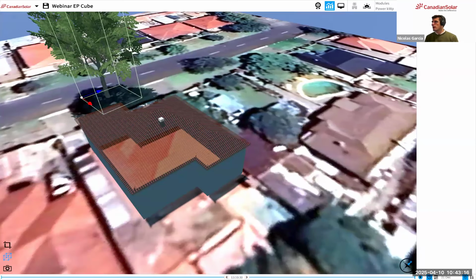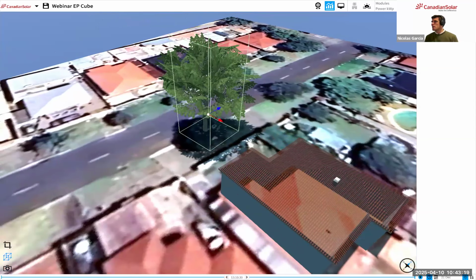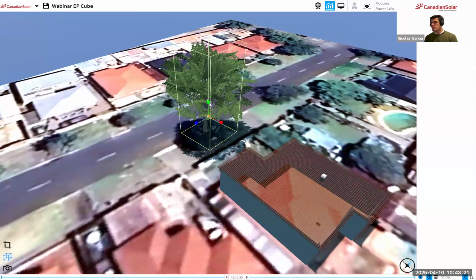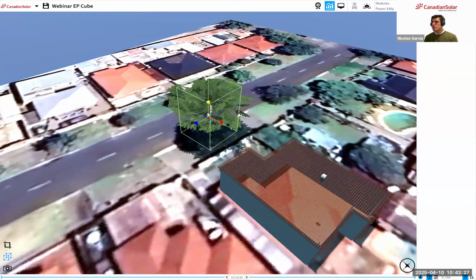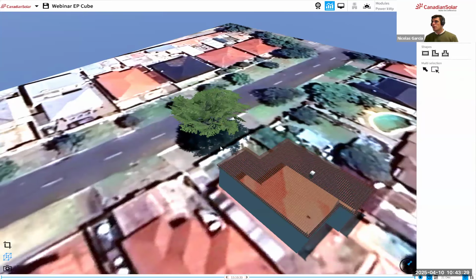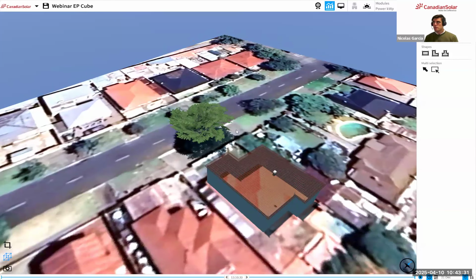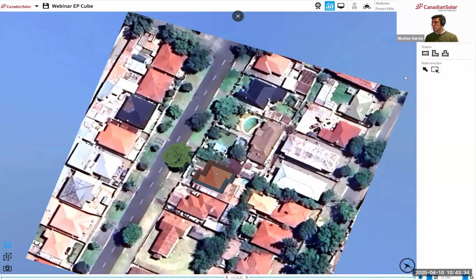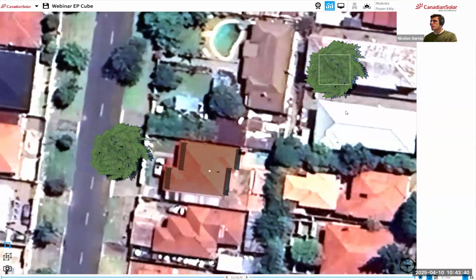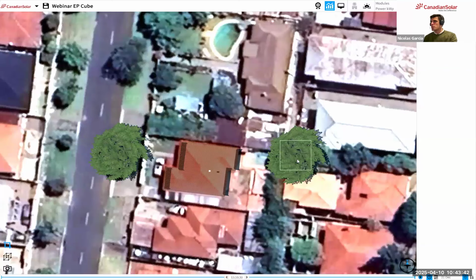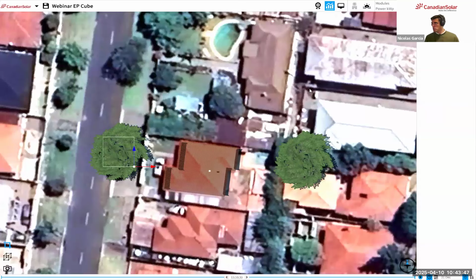into the 3D view, and on the object, we select the object and we click on scale. Here we can adjust all the parameters. I'm going to set it a little bit smaller. Another way we can set the parameters is by selecting the objects and already defining the height, for example, here of 7 meters. Then the tree that will be created is already within those measurements. I'm just going to leave them as they are